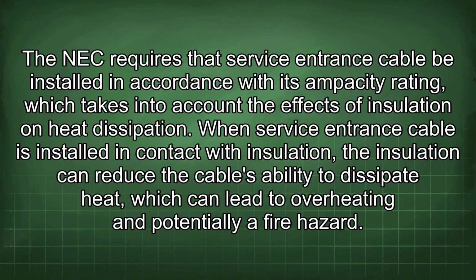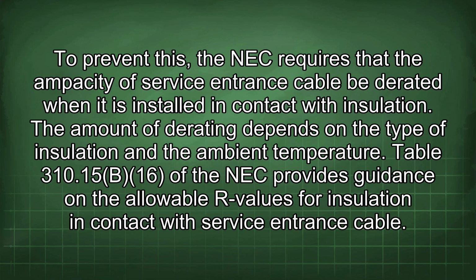When service entrance cable is installed in contact with insulation, the insulation can reduce the cable's ability to dissipate heat, which can lead to overheating and potentially a fire hazard. To prevent this, the NEC requires that the ampacity of service entrance cable be determined when it is installed in contact with insulation. The amount of derating depends on the type of insulation and the ambient temperature.